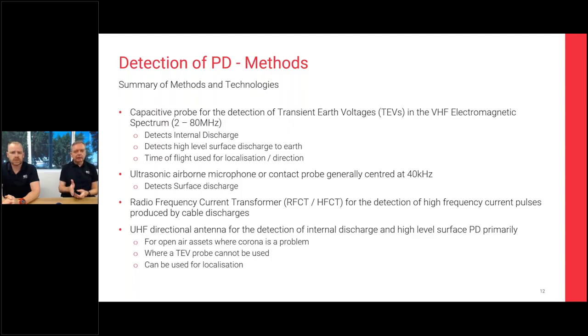Ultrasonic is directional, pointing in towards the termination. This is not going to help you for testing down cables, but it is a significant failure proportion of, say, dry terminations at the termination point where we've got cross phases, for example, which we'll come to later.